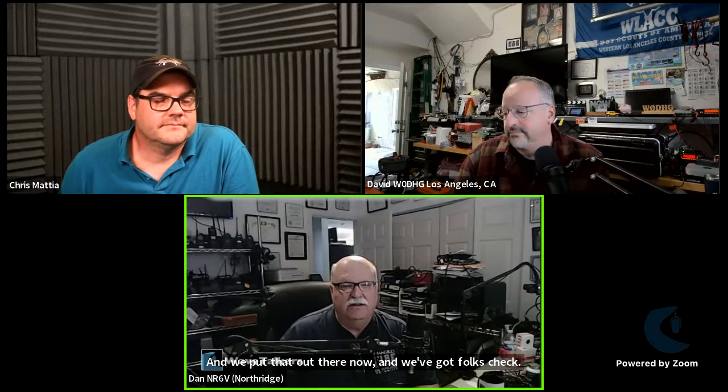And this got some of our members. Most of our members weren't aware that their radios could pick up AM, and we've put that out there now. We've got folks checking their radio and the spec sheet to see if they can pick up AM. Some of the radios, like the Yaesu FT60, will receive 243.0. It'll tune up into that range. That's a little unusual, I think. Most of them don't, but a lot of them will do 121.5. Almost all of the Yaesu handhelds are wideband receive, so you can tune a lot of that, and you should be able to receive with those radios.